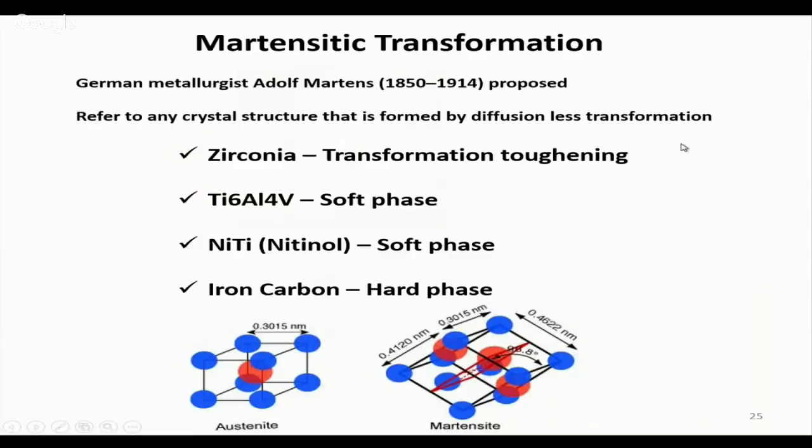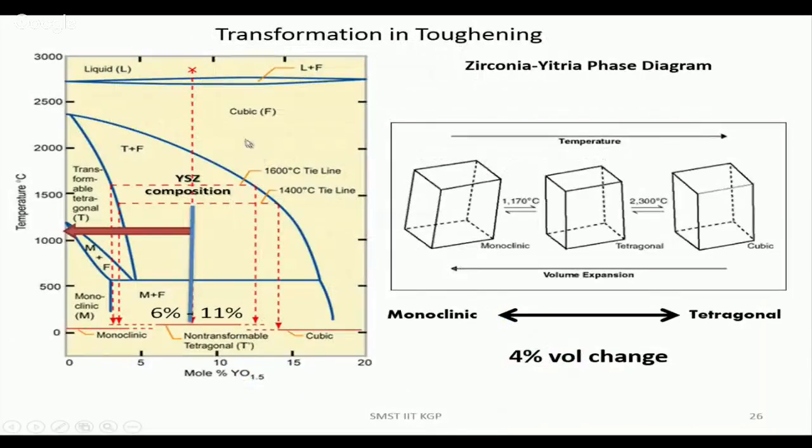So now we have either alumina or zirconia. Alumina is alpha alumina and zirconia is cubic zirconia. These are like a matrix. And when you have monoclinic or tetragonal zirconia, they are the toughening agent, right? So I want a phase where the majority is cubic zirconia or alpha alumina, but we should have some dots of either monoclinic or tetragonal or a mix. Is it clear to all of you? Is it clear or is it too confusing?